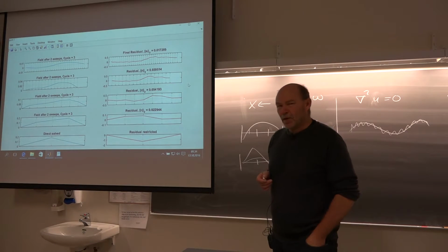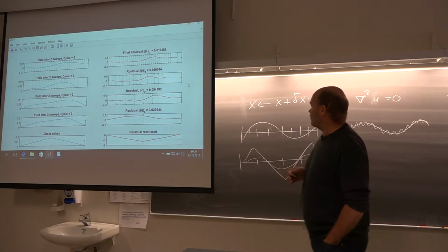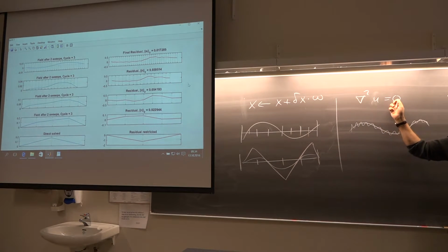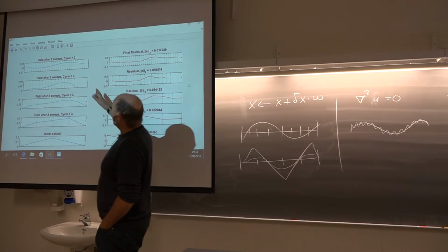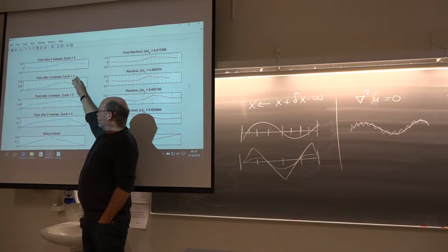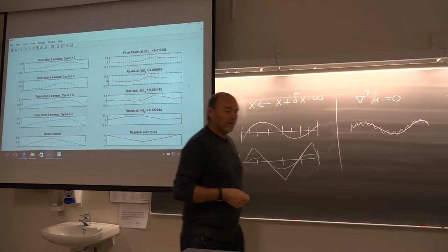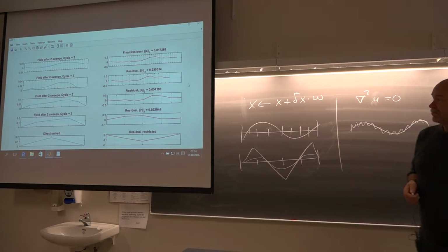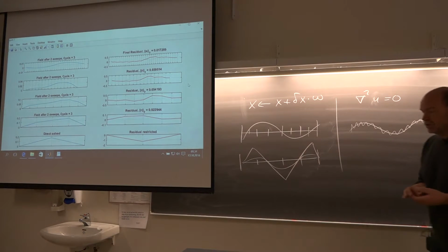Also, you have a problem when it comes to the boundary conditions. For this test case, it's very simple, say zero gradient on the boundaries, for instance. Okay, fair enough. On the fine mesh, you have the physical problem at hand. You know what's going on. But on all the other meshes, the sub-meshes, the coarse meshes, you also need boundary conditions for them. So that's going to take some time to do the programming, I can assure you. Not easy. So all meshes have to sort of have their own boundary conditions.